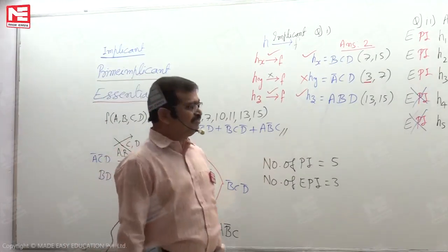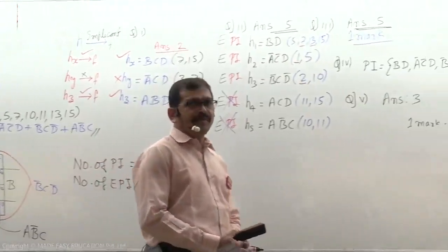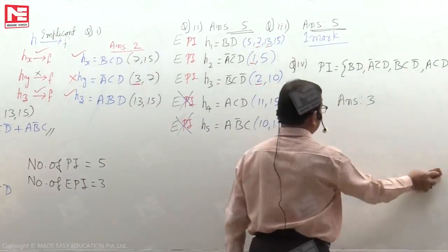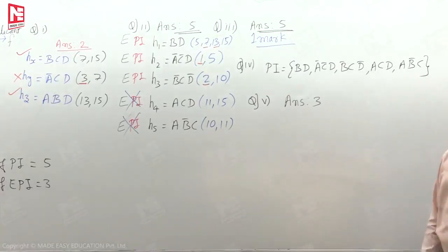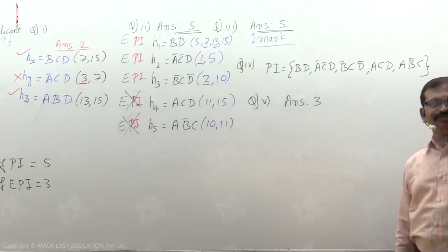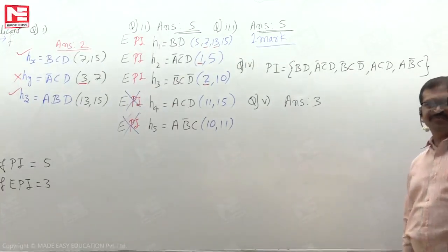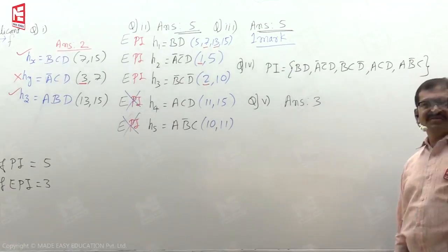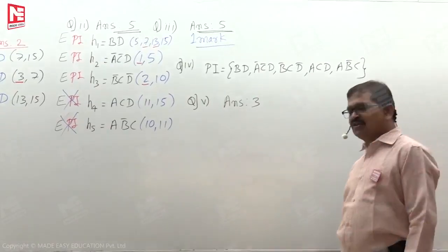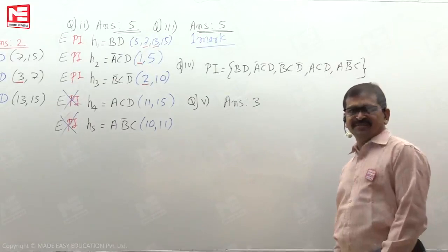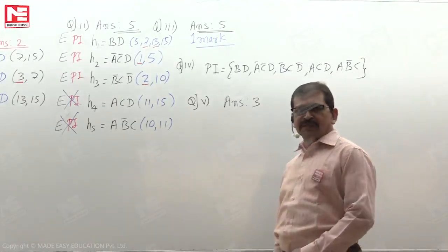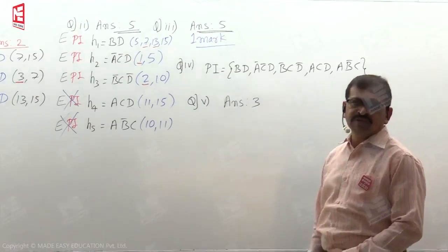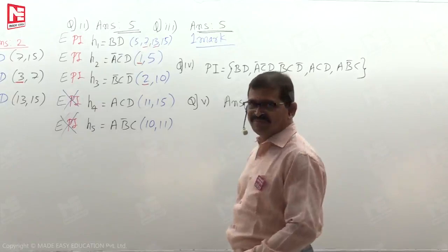So better note down the statement. The number of essential prime implicants to the given function is equal to the number of all possible largest size subcubes in which at least one cell is without overlapping. That is the statement possible to give.